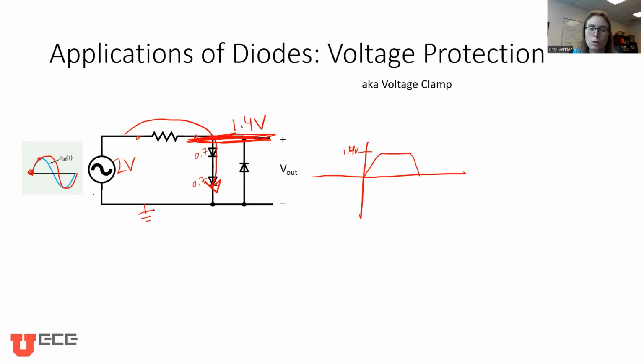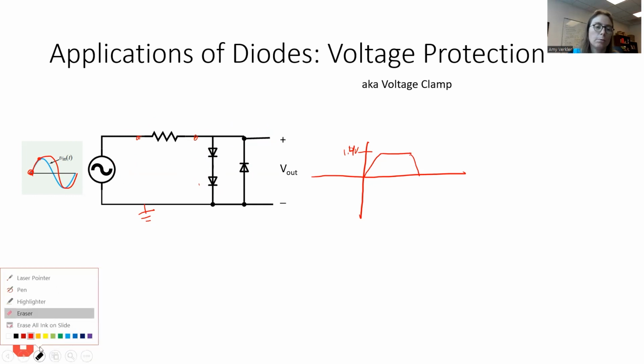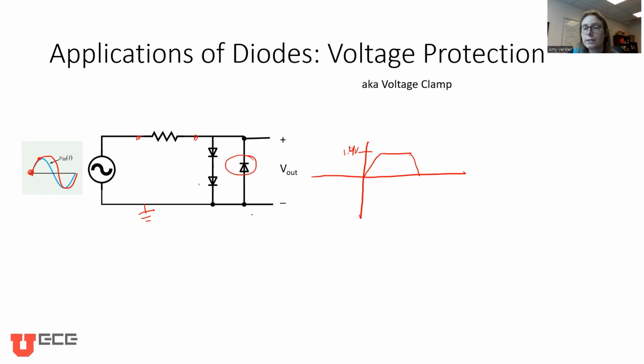So we expect, well, let's erase our pictures there. Okay. We expect this diode to turn on once the voltage is at least negative 0.7 volts. And so what happens before that when we're at negative 0.5 volts? We have negative 0.5 volts here. Again, there's nowhere for current to flow. These are off. This is off. So there's no voltage drop here. So this is negative 0.5 over here. So the same thing as we're tracking.